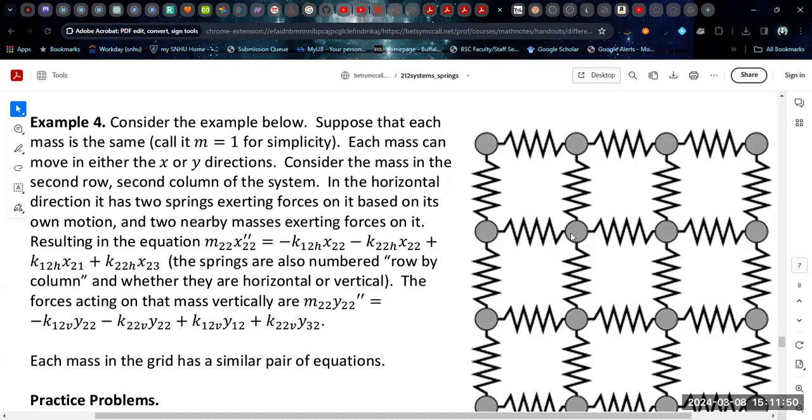If you had a 3-dimensional grid, you might have a layer on top of this, and then you would have a similar set of equations in the x direction. Now, in this example, we're assuming that all of the action is taking place essentially at a right angle. So the x springs are only affecting the x direction, the y springs are only affecting the y direction, and they don't change as the angle changes. If you get a much more complex crystal structure, you may have something acting at an angle to each other, a bond with the next layer up and one particle over.